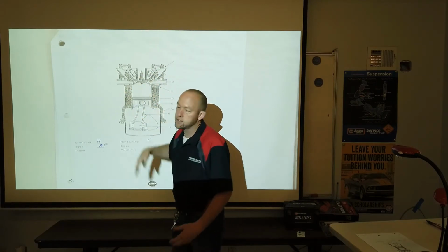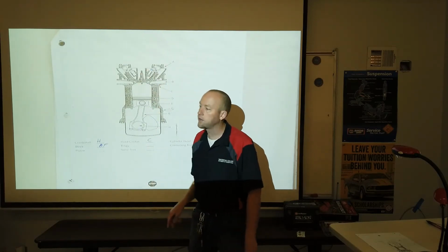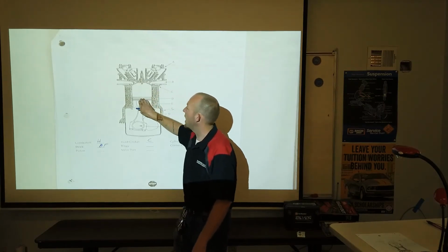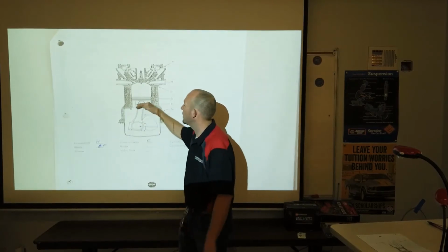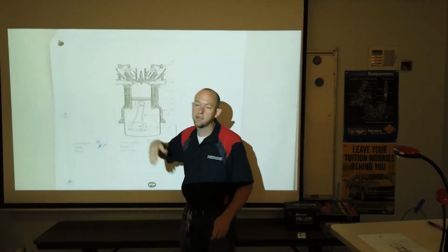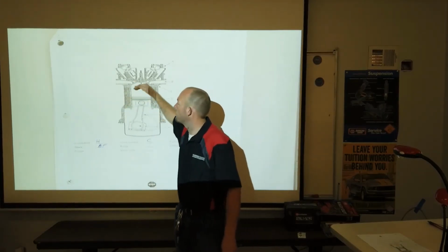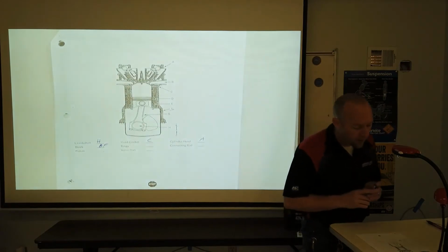And then is where our combustion chamber is located, with our spark plug right down the middle. This area below the cylinder head and above the piston, we would refer to as the combustion chamber. When the piston is all the way up at top dead center, we're squeezing that air fuel mixture down into its smallest volume, and that is literally our combustion chamber there.